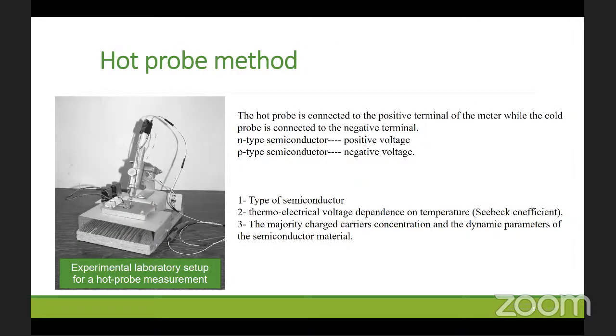The carrier mobility and concentrations for the polymer nanocomposite can be measured by different methods like the 4-point probe and Hall effect measurement. The main problems in the application of these methods to thin film parameter measurement are in the measuring device sensitivity and in the complexity of the specific sample preparation.